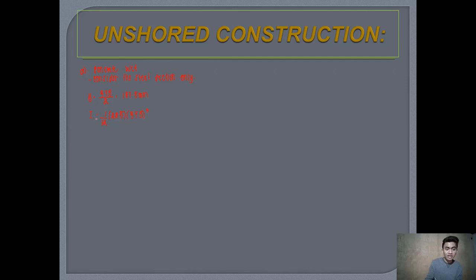Now the centroid of this part is at the neutral axis, so no need to add AD squared. Instead, I will subtract the moment of inertia for the two rectangles, as I have said earlier.